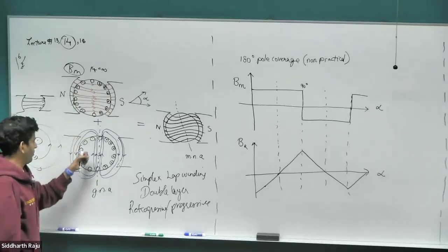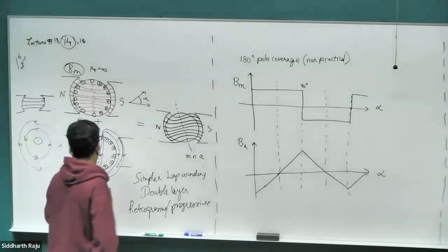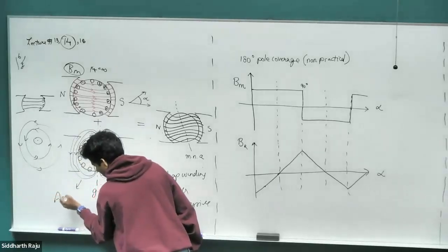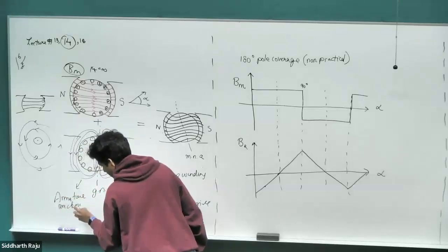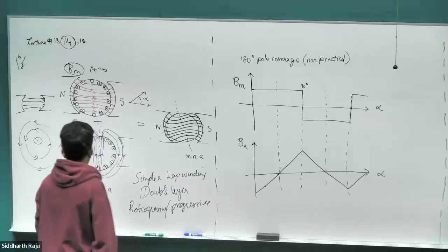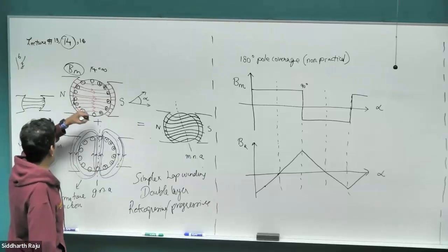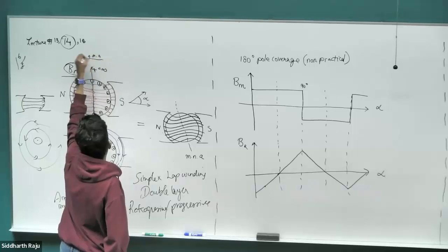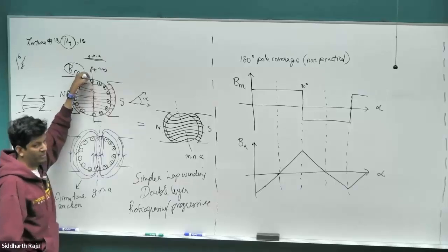When we look at the whole set of conductors, there are field lines created by these conductors which have an effective magnetic field. This is called armature reaction when it interacts with the external magnetic field being generated by the magnet. Without it, this would have been the ideal way in which the magnetic field would have been, and the center point is called the geometric magnetic axis. This is where the EMF would have been zero as well. Whichever coil was in this position is where the EMF would be zero.